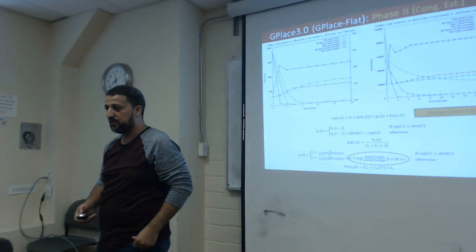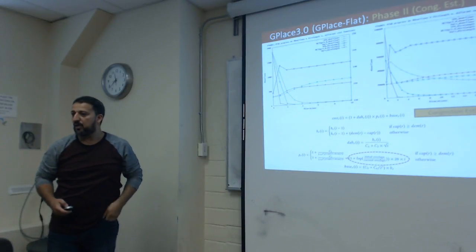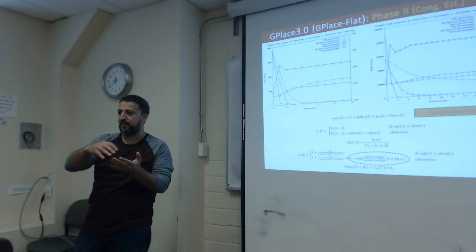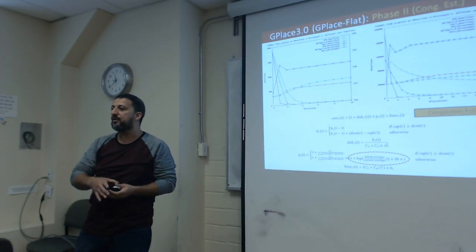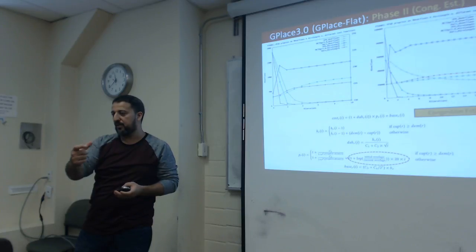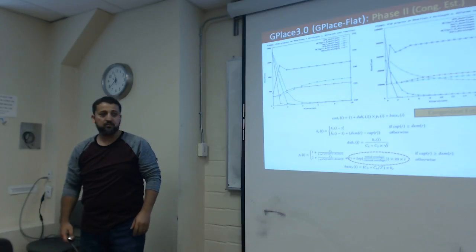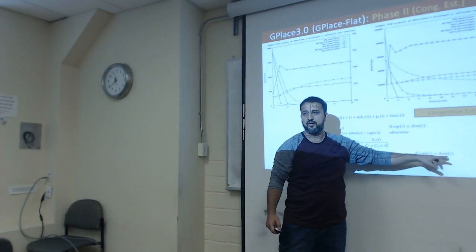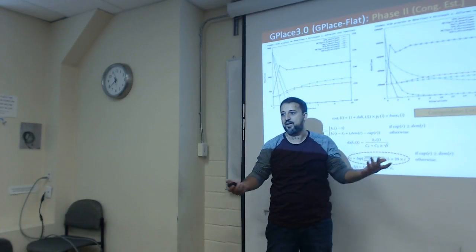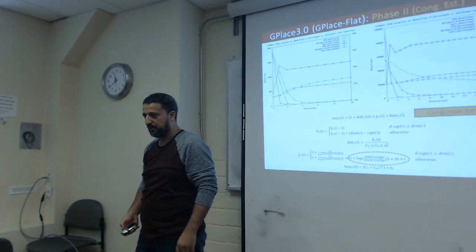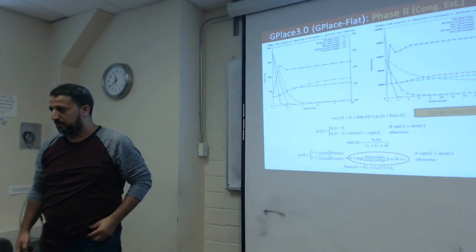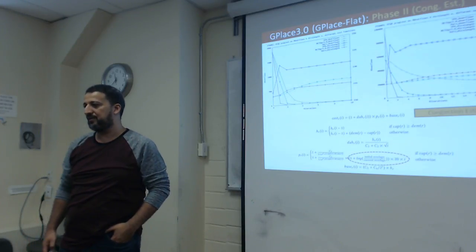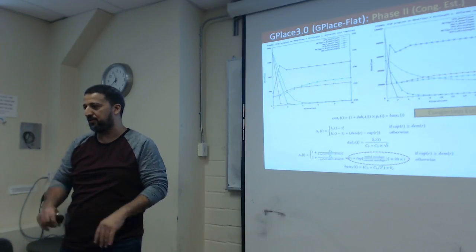Just on the definition of overflow here, Ziad. Okay, so the definition is when you do the routing, do you assume W tracks per channel? You have a channel capacity, and your overflow means you exceeded the total number of tracks per channel? Yeah, the capacity for that edge is less than the demand, so you have overflow. So that doesn't take into account the switch block connectivity or anything like that? No, that's global. Anything within the switch, we ignore it.